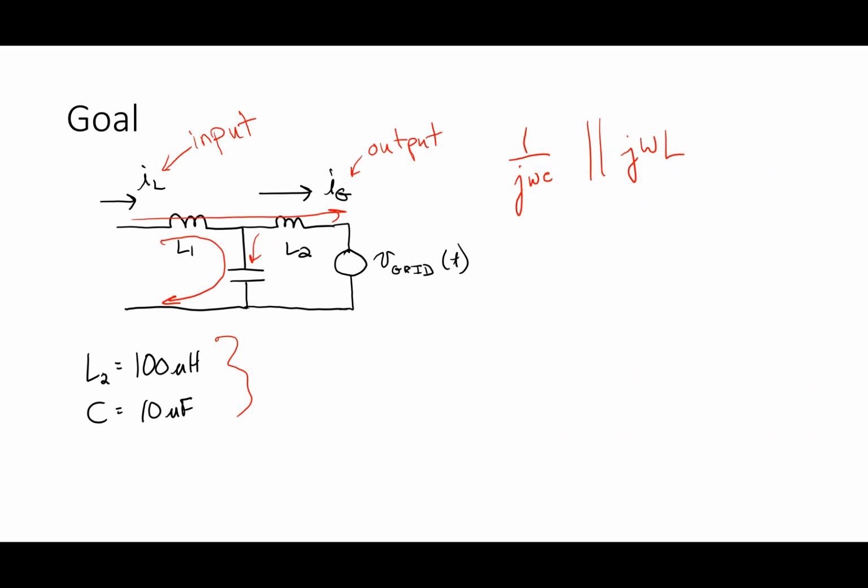It's the physics of the inductor and capacitor, which means it's effectively trying to slosh the energy at high frequencies through part of the loop here, but the low frequency energy is able to make it through to the grid. So the low frequency stuff is basically flowing this way. The high frequency stuff is flowing this way. Do those currents have the same magnitude? Those currents depend on whatever the voltages are that are driving them, right? They don't necessarily have the same magnitude.